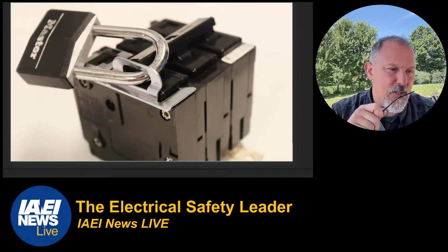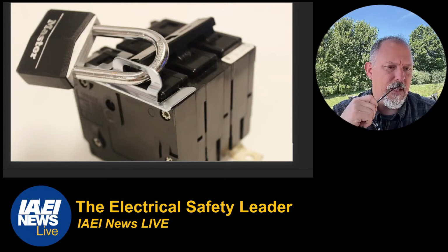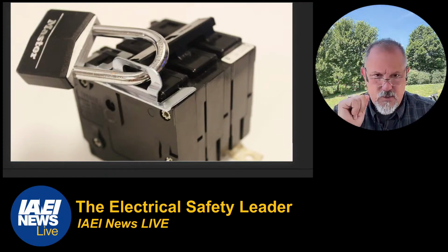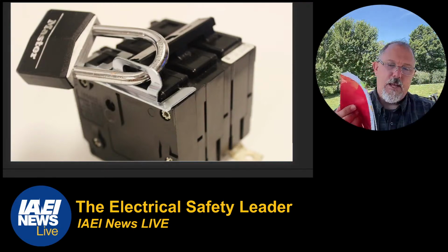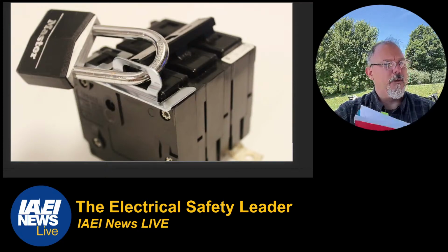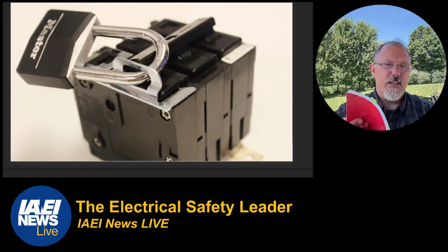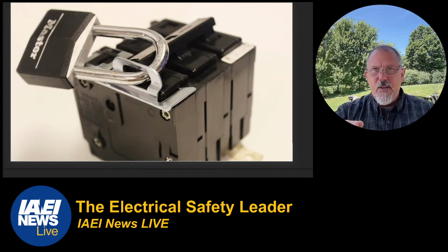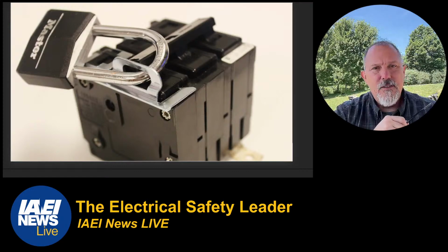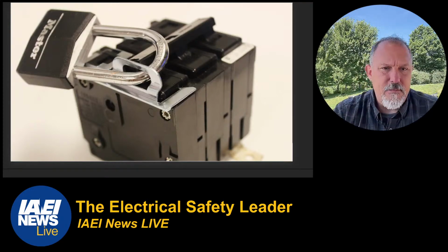Let me just look at some of them. Would you say it's risk category 1 per 70E to open a 4-square box with insulated conductors while energized? Risk category 1. So would I say that? Well, Willie, you've got to follow 70E. I don't know what you mean by risk category 1. You're talking about an arc flash PPE category 1? What section of the 70E are you talking about from a risk category? I mean, if it's an exposed conductor, you have the risk of shock, period.